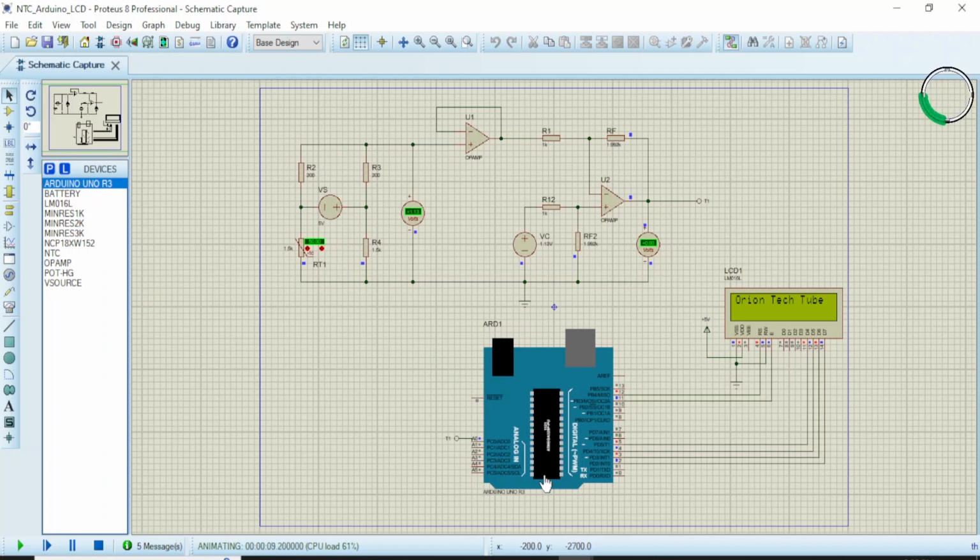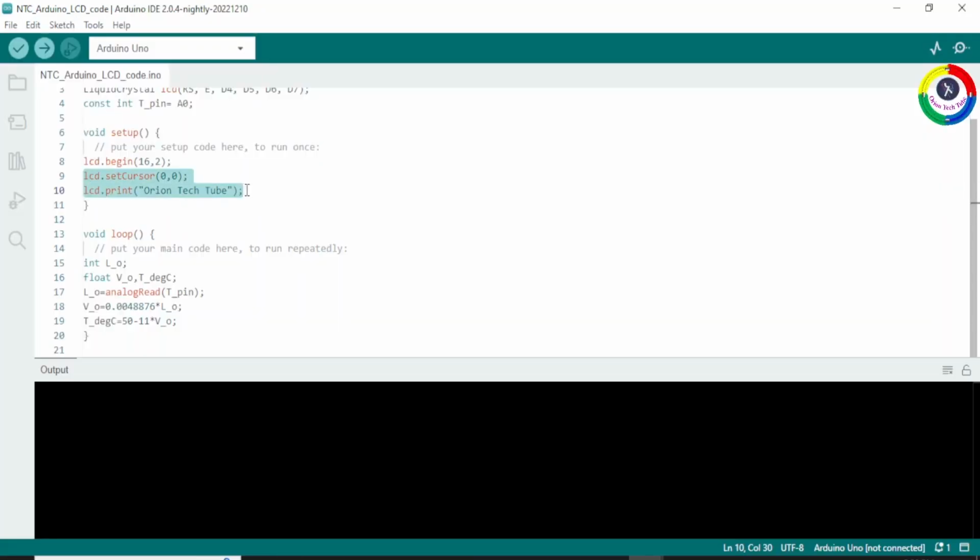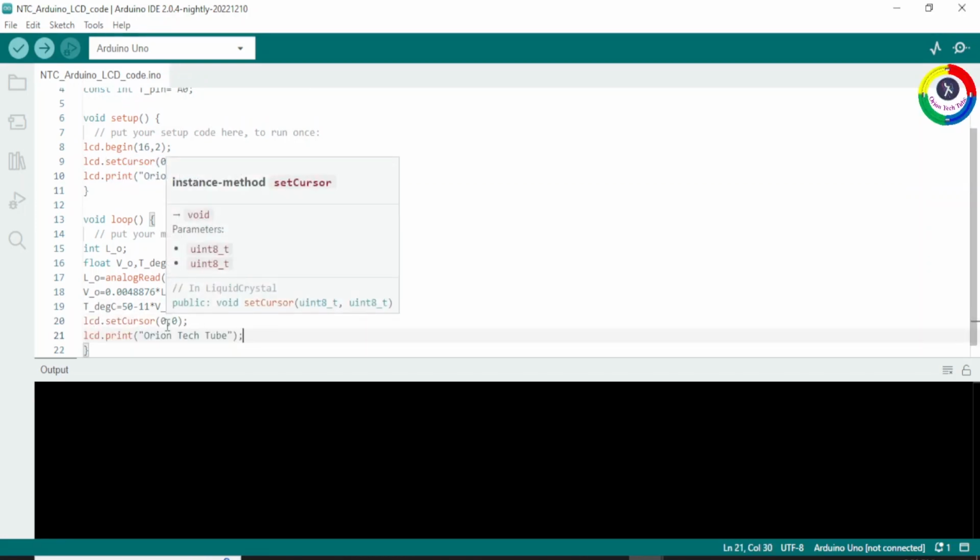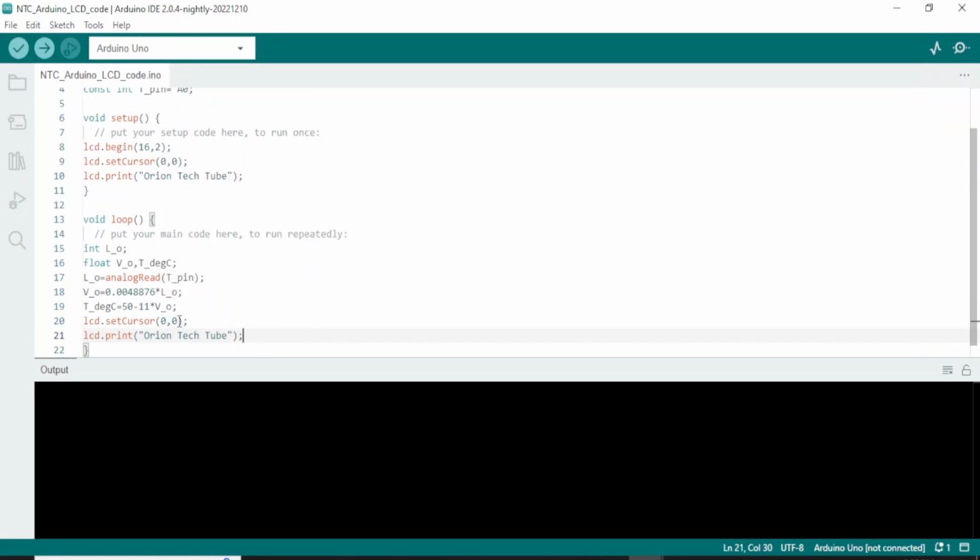Next, let's display the measured temperature on the second row of the LCD. Go to our program again. Inside the void loop section, here to write text at the first cell of the second row, that is indexed by 0, 1, we write Room Temp, short for temperature. Let's count the characters. These are 10 characters, including the space between room and temp. So we need to write this text in the second row of the LCD. Next to this text, we need to display the temperature value.